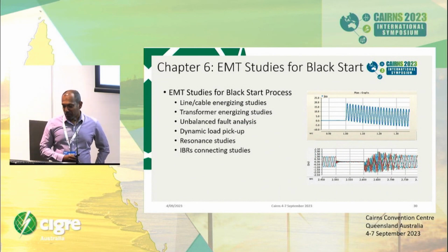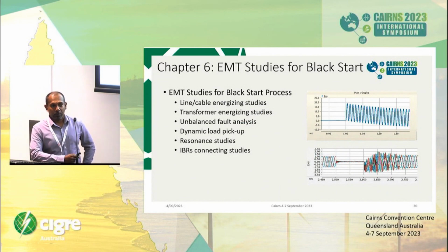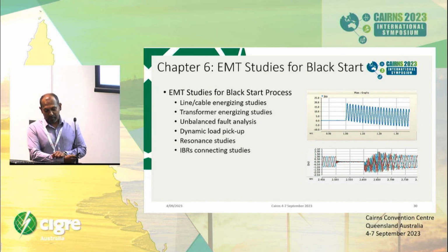As time permits, I don't want to talk about many topics, but let's concentrate on EMT studies, because there are a few things that we can highlight through EMT studies that cannot be seen in phasor domain simulations. The examples mentioned here are line or cable energizing, transformer energizing, and obviously unbalanced fault conditions.